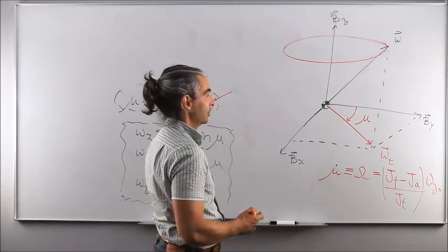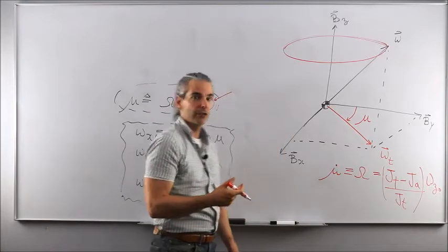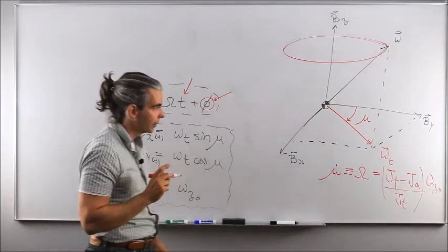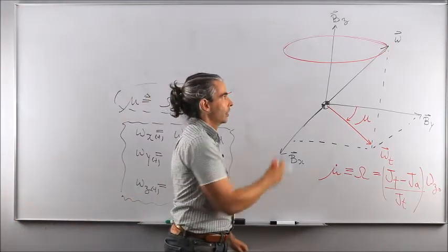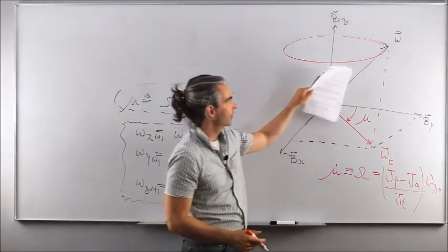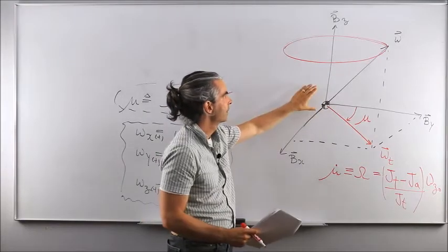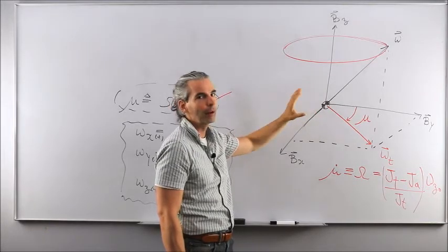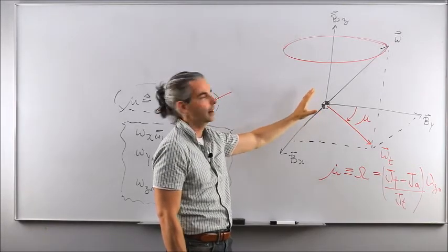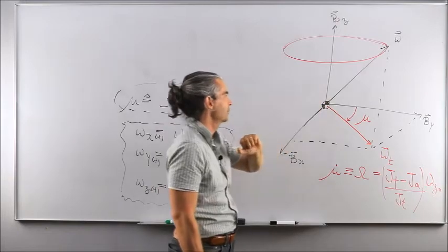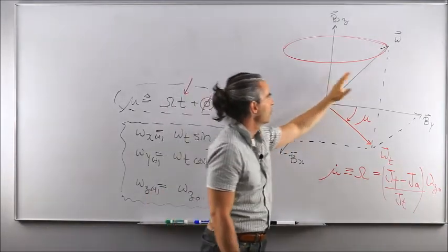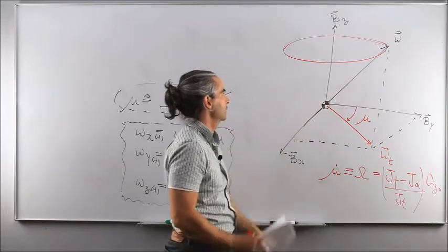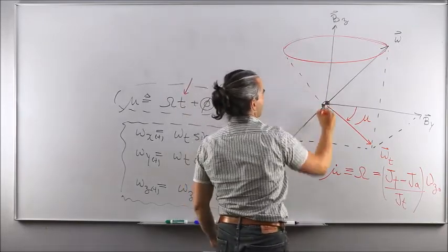That's what it is. So this is the three-dimensional interpretation of the equations we derived for omega x, omega y, omega z as a function of time. And this told us that, again, the motion of the angular velocity vector seen from that body fixed perspective, not seen from the inertial perspective, completely different, okay? But seen from the body fixed reference frame's perspective, draws a cone about bz, essentially, right? Does that look like a cone to me?